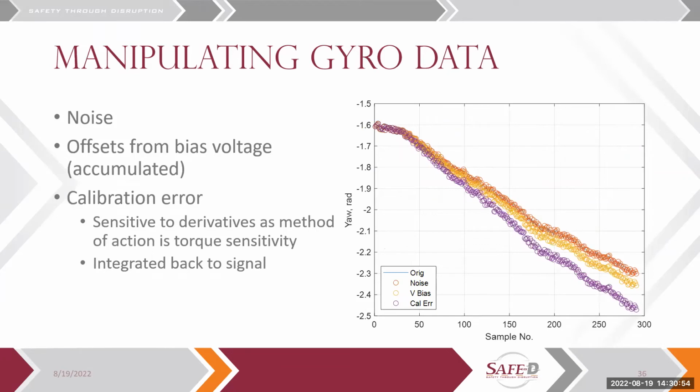Next in the IMU stack, we have GYRO data, the gyroscope. So here we had to do a little bit of integration of error. We had a bias voltage offset that then gets accumulated because the gyroscope integrates over time to calculate what the different 6 degrees of freedom are. So you can see all of these accumulate over time in the gyro, the errors that we add in.